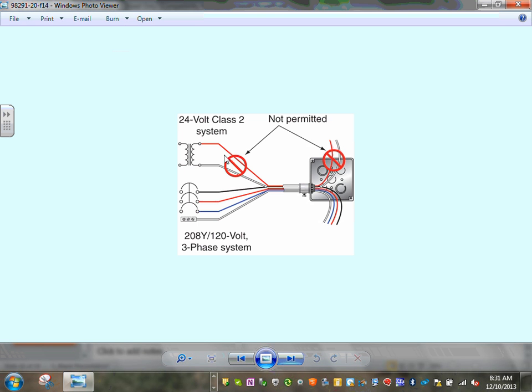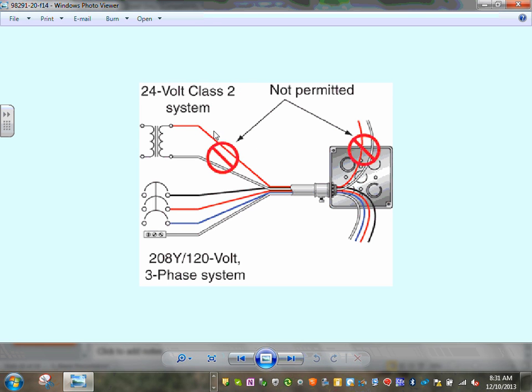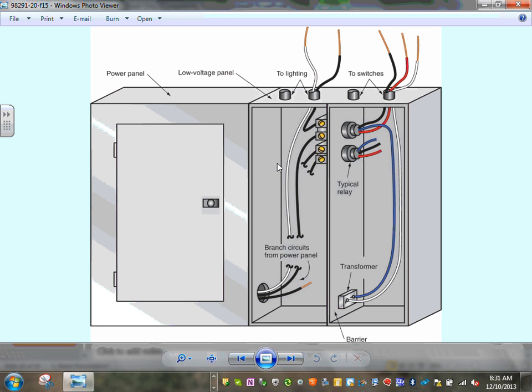And they're all low voltage. The last thing I want to say, guys, low voltage is called a class 2 circuit. You cannot put a class 2 circuit with the power in the same box or conduit, right? You have to separate them. So just be aware, different conduits, different wires, different boxes. That's required by code. First, anybody knows why?